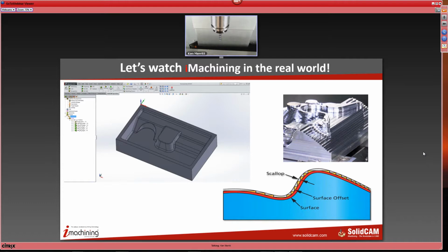All right, well, I'm going to talk a little bit about iMachining in the real world and what it actually does. To start this off, see this part on the screen right now, this little coin dish type of cavity mold, the one over on the left. This is what we're going to cut today as part of our standard presentation. We want to show several things. iMachining's 3D roughing is what we're going to be showing you today and how it works, and I want you to pay attention to the scalloping and how well it finishes out the part.